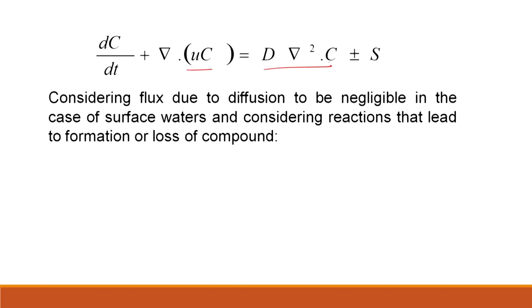And for surface water flow, typically because transport due to advection is so fast, we can typically neglect the diffusion term, and most of the aspects we are going to discuss in class, we are not going to look at it. But as we saw for the example of groundwater, where the flow velocity is less, diffusion is remarkably important. But for most other examples that we are going to look at, at least in this class, because advection is so fast, the mass flux there is going to be much higher compared to diffusion. That is why we are going to neglect diffusion, and I think that is what I have here.